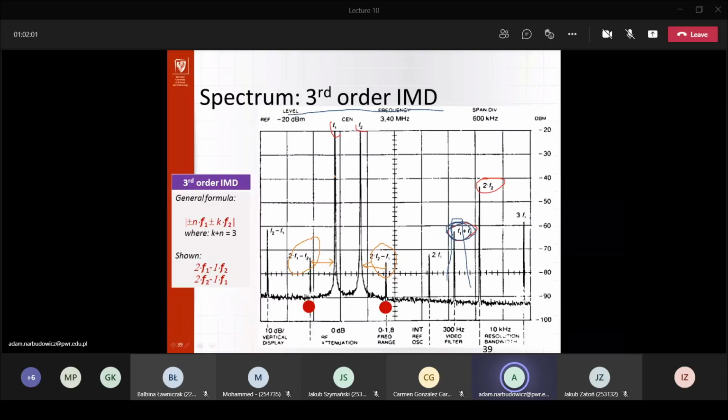So here we discussed only two input signals, and you can see there are already quite a few peaks being generated. Now, if you add, let's say, 5 different signals, each of them will first generate harmonics at integer multiples of themselves. Secondly, every combination of those signals will generate second order harmonics at the sum and the difference, then third order harmonics that you see here. And this will be happening with every one of those 5 signals.